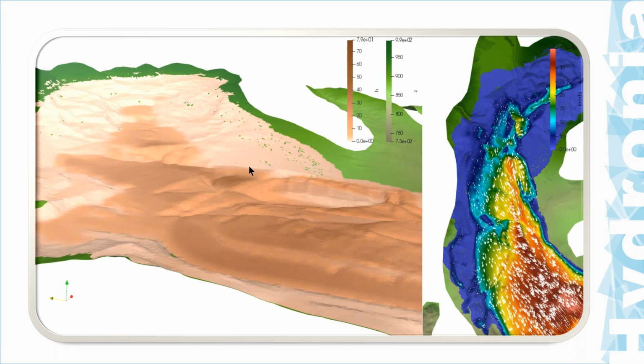I have a question in regards to comparing the results. Bingham has a bigger area than Coulomb or Quadratic, but the mud stopped upstream. Yeah, in the Bingham formulation, the runout was very short, but the area that covered was much larger because the depths were much higher. So it covered more area in the upper part. So adding one and comparing with the other, you find out that the covered area upstream is higher because of the higher depth and the extent that the higher depth generates upstream.